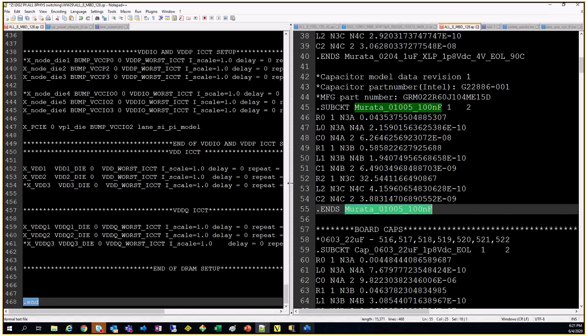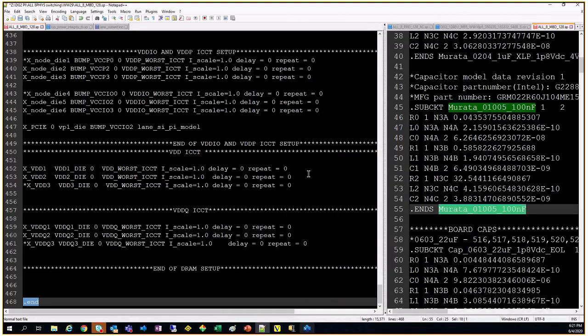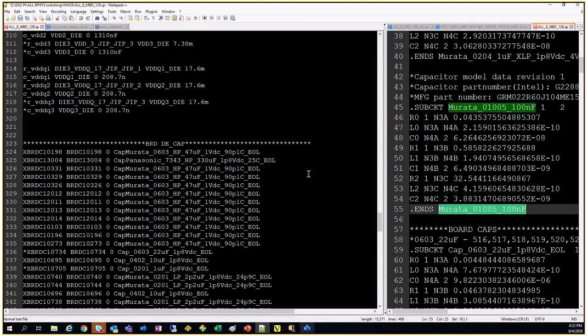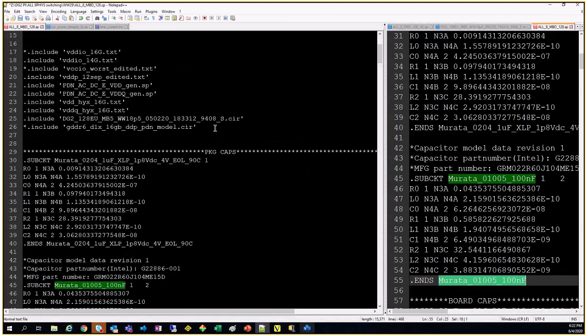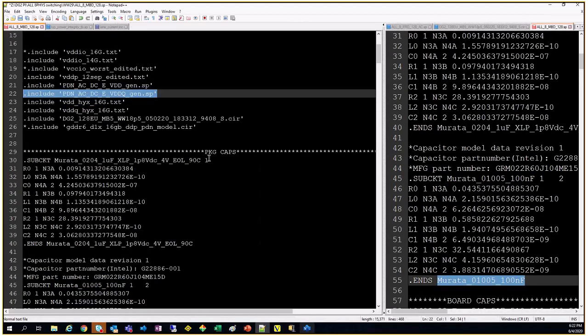One very important thing in SPICE, which is going to be the weird thing, is how to include all the files. If you see here, you are hooking up subcircuits from different files. How to include a file is .include. In quotation marks, you can include the file name, the txt files you're hooking up. When you build your deck, you understand which files to hook up.